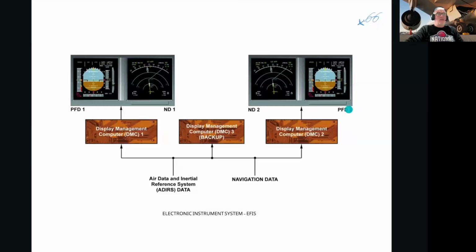When I say pictures, the outside ones, the primary flight displays, are the outboard ones, and this is permanent. So this is a permanent display, but the navigation display is a display unit. At the moment it's showing as a navigation display, but these are display units which are switchable. They're multifunction display units because they can display several other things, which we'll see further down the line.